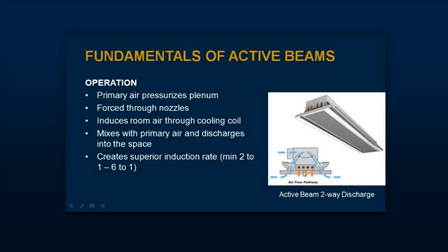They come in an active, which incorporates the supply air to the room, the ventilation air often, and then we have passive. So I'm going to first describe very briefly active beams, and again refer you to our library of webinars if you want more in-depth on how this product is selected and operated. But in essence, an active beam could be considered an induction terminal unit.